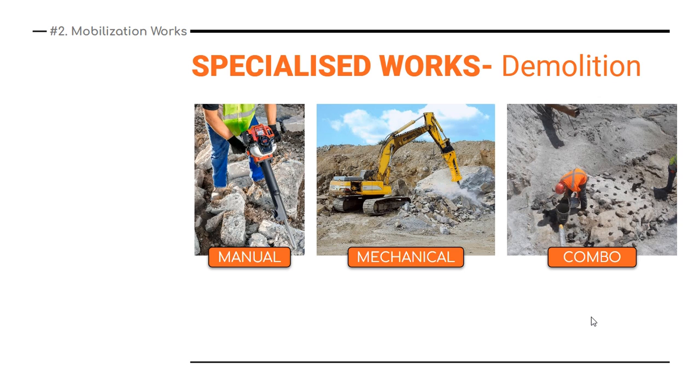In case of mechanical, the same thing happens, but here also you need to have a large area so that this jackhammer mounted backhoe excavator can reach the site, and there should be plenty of area. So again, if the site is accessible from all the directions, then go for this mechanical kind of way for demolition of big rocks.